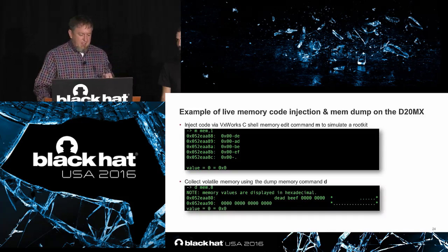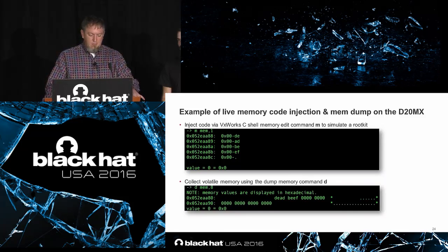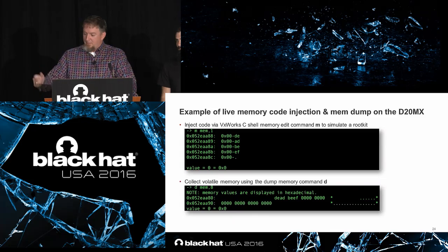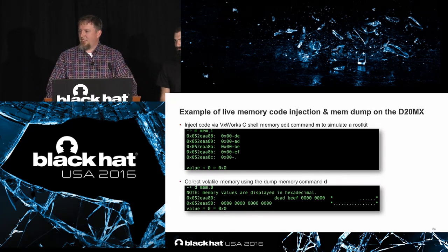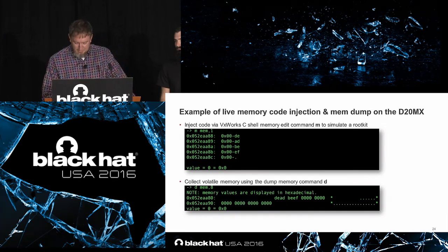So this is where we get into memory. So let's say I have an infected laptop, and this engineer connects it to the controller, and it injects in memory with the VxWorks Seashell memory edit command M. So we put DEADBEEF in there, and we collect the volatile memory out, and we see that it's DEADBEEF. So this is not really a bad thing, but someone could inject maliciousness in there.